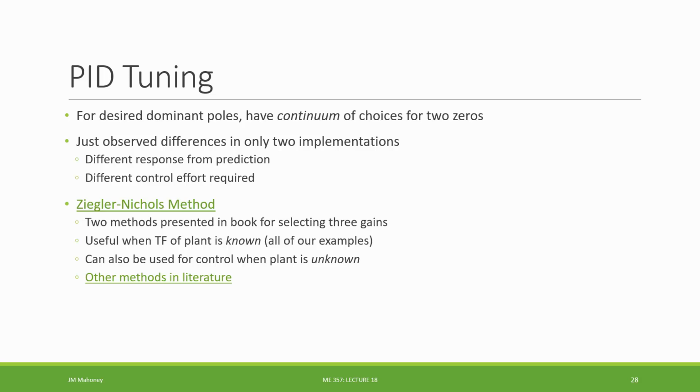Another thing we didn't observe here, but that is going to be a concern in real systems, is that the derivative term we're using is highly susceptible to any noise we have in the measurement. In all of the simulations we've done, all of the systems we looked at in this unit, we've had perfect sensing, perfect actuation. There was no noise in any of the measurements. Once we introduce a little bit of noise, this derivative term can get very, very large, because we're going to have sudden jumps in the values that we're measuring.